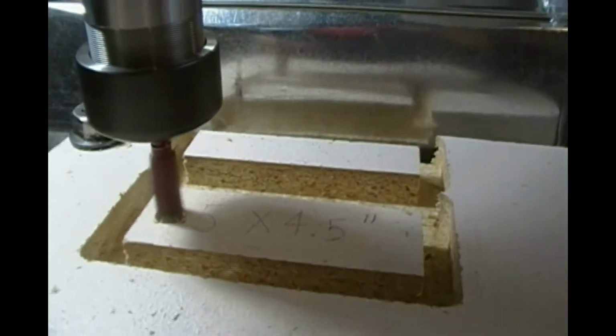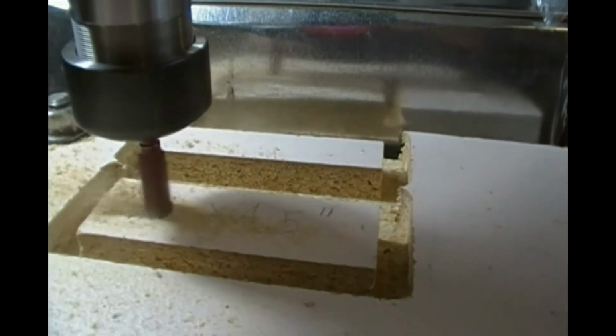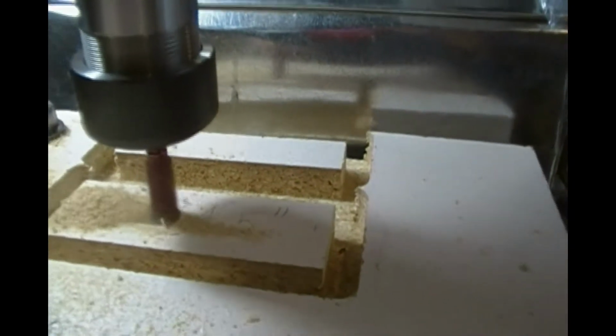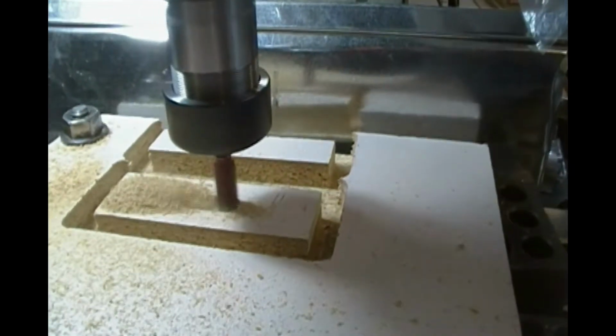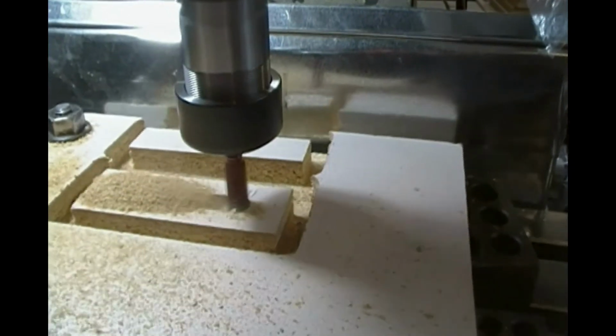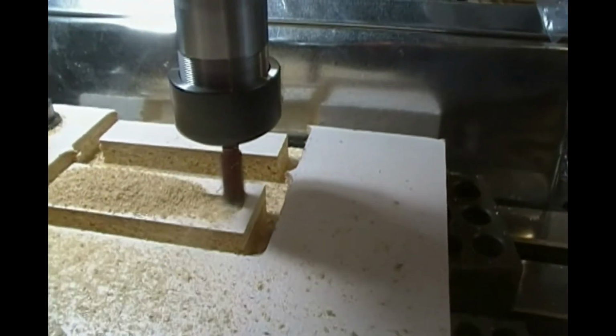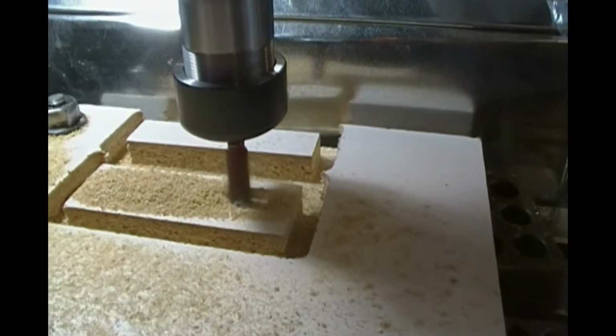Making only perimeter cuts is a quick, rough, and tough cut. The pockets' bottoms may have to be cleaned up slightly, and the side pressure when cutting could possibly damage your borders, depending on the thickness of your border.